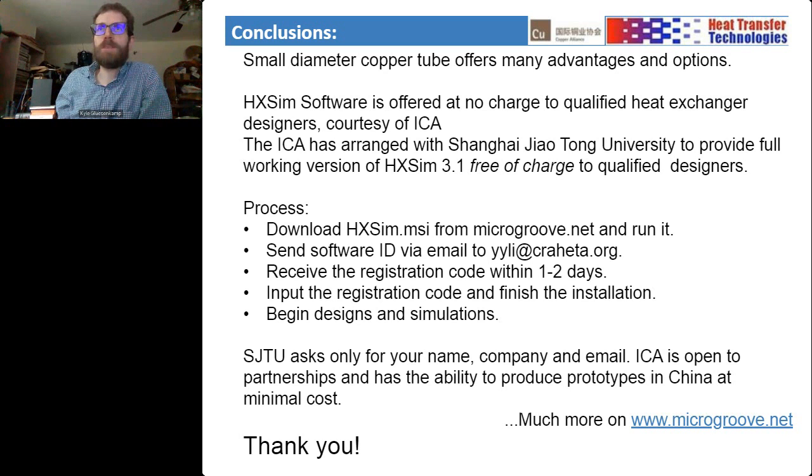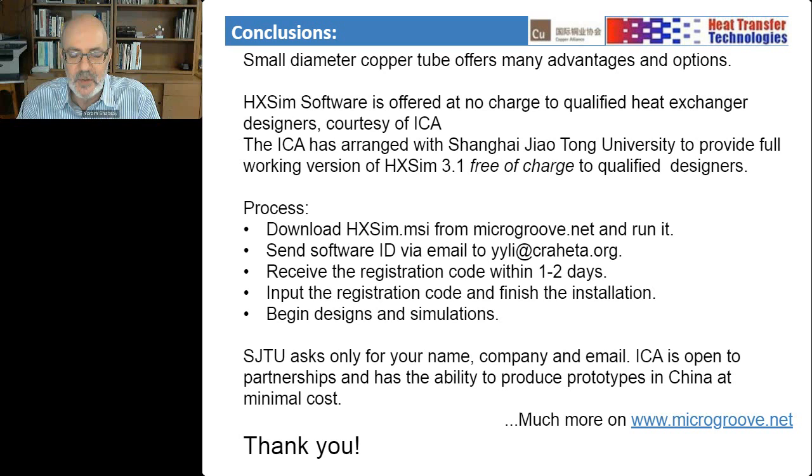So Yoram, Craig Sai has the same question that I did. In your condenser wrap simulation results, did you change the condenser routing, like single pass versus multi-pass, in order to compensate for the pressure drop of the smaller diameter? Yes, excellent question. Going to smaller diameter tubes, as you can imagine, will increase the pressure drop because the tube is smaller. So multi-pass is usually the way to go to drop the pressure drop to the previous level or your baseline that you compare against.